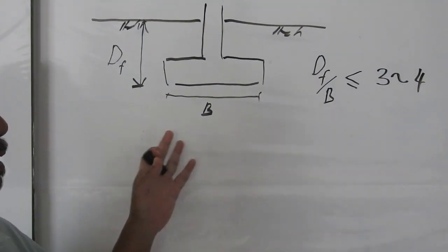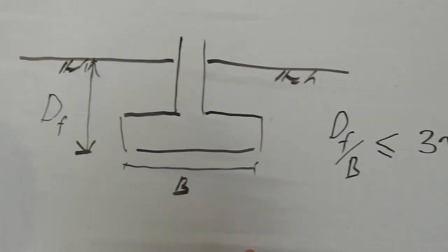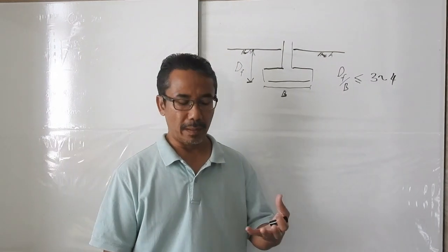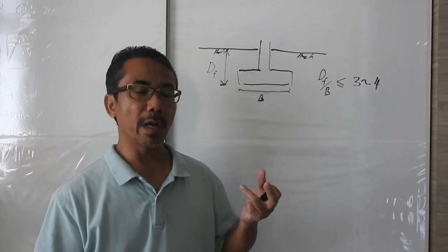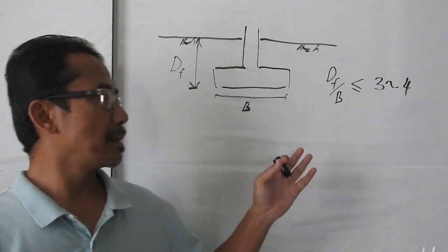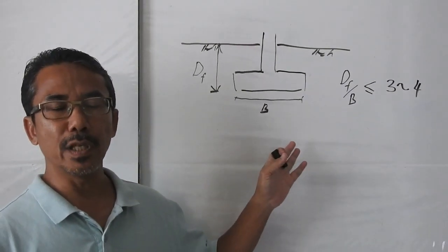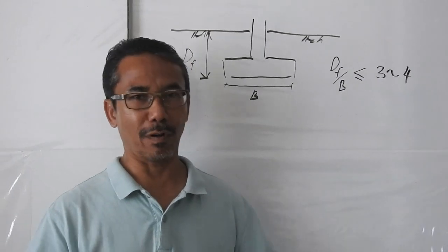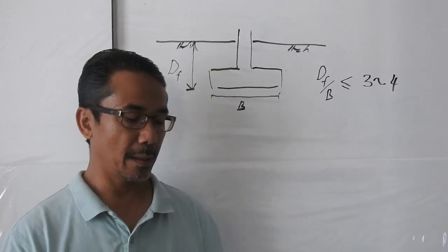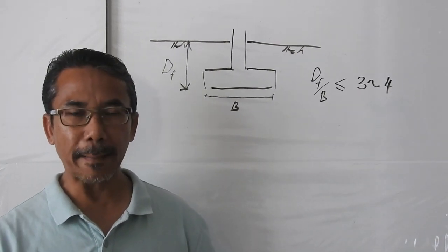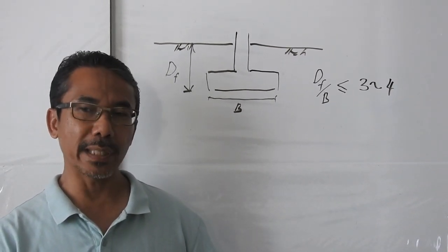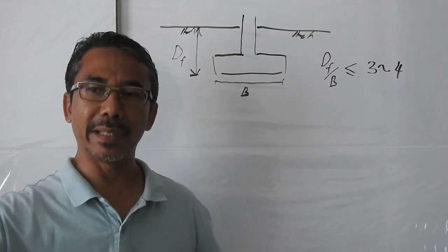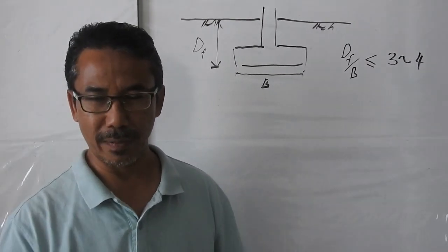Okay, in terms of a shallow foundation, there are several equations that we can use to determine the bearing capacity. Right? We have Terzaghi's equation, we have Meyerhof-Hansen equation. Terzaghi formulated 3 different equations for bearing capacity of shallow foundation depending upon the shapes of the footing or the shapes of the foundation. One equation for strip footing, meaning the ratio of the width of the footing to the length of the footing is very, very small, meaning the length of the footing is very large.